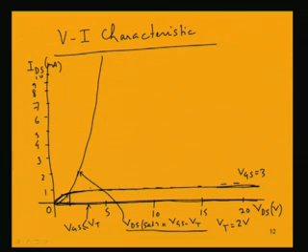It is 1 volt for VGS equal to 3. Now, say VGS is equal to 4, then we will get a saturation VDS value of 4 minus 2, which is equal to 2 volt. So, we will be getting saturation at a value of 2 volt, say for VGS equal to 4 volt.